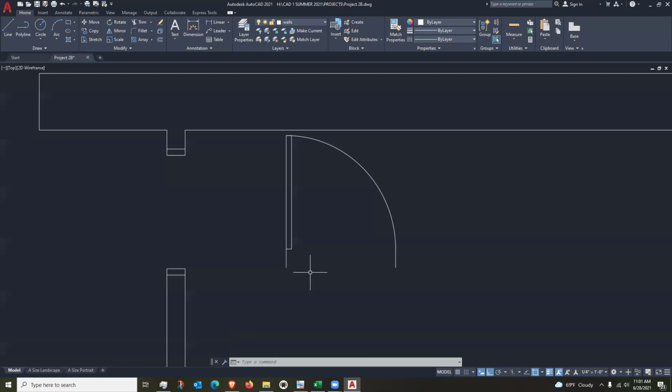You need to look at the construction of the wall. Normally the wall construction is 4 inches of brick on the outside, then an air gap, then 8 inches of concrete block, and then there may be some drywall that's furred out on the inside of the wall.